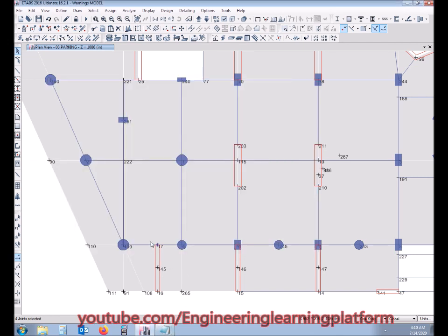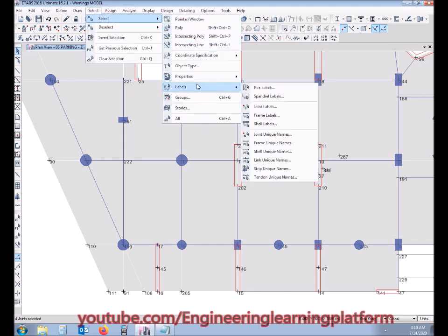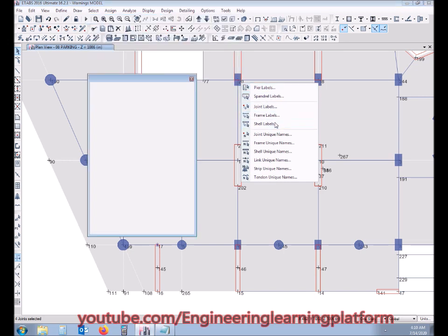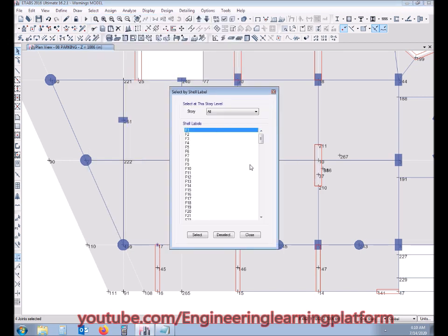So either we delete the joint if it's unnecessary due to revisions in the drawings from the architect. We make changes in the structure, so the unnecessary joints are left here, which sometimes also causes errors in model analysis, giving higher values of drifts.